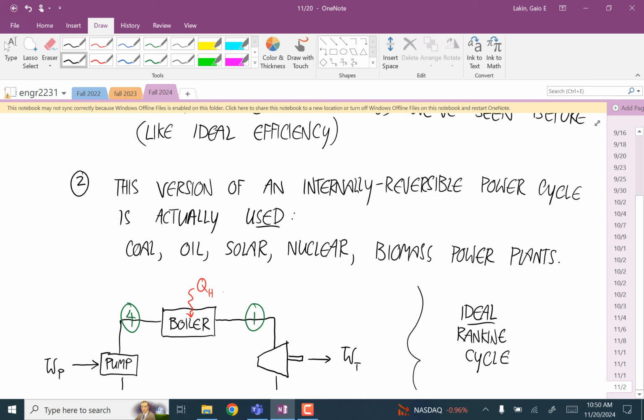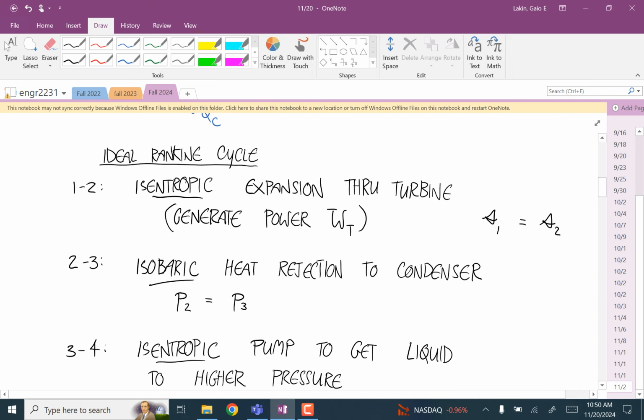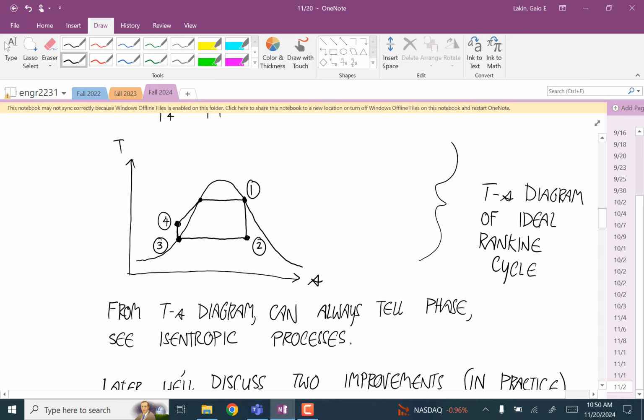Can you think of latent heat as like the relative width of the vapor dome? Yes, exactly. Think of it that way. I mean, it depends. What it is, I guess, is how much energy it takes to go from one side of the vapor dome to the other. Depending on what vapor dome you're looking at, here the width of the vapor dome is an amount of specific entropy, but it's how much energy it takes to go from one side to the other. So in terms of energy. Yeah, so in a T-s diagram, it's the width from one side to the other. That's correct.